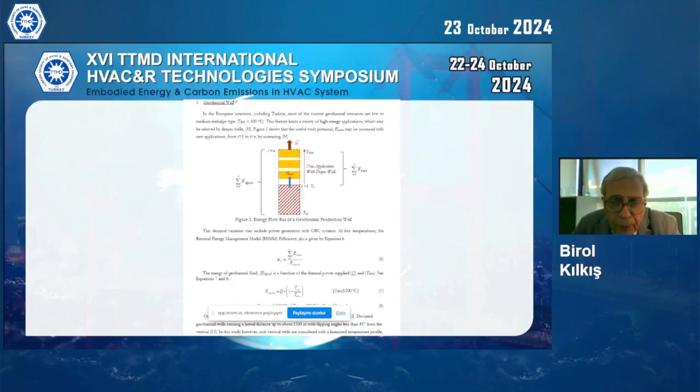So there's an optimum. To define all these on a common base, we define a rational exergy model efficiency, sigma R, which is the ratio of the total demand exergy divided by the supply exergy, which is in this case the geothermal well exergy. And it can be defined by equation 7 and so forth. And we can go further.